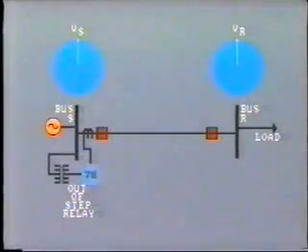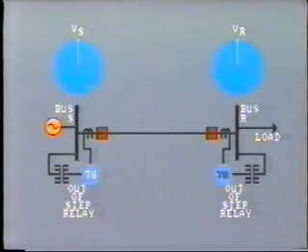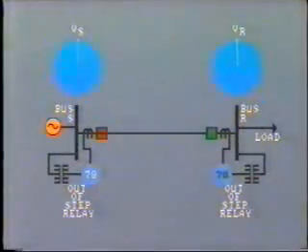The time interval between the first and second zone operation is important. The relay is set to indicate an out-of-step condition where the time interval is 60 milliseconds or more, since short time intervals, say 5 milliseconds, would probably be caused by a fault on the line. The out-of-step relay at bus S operates to trip its breaker. A similar relay located at the receiving end bus operates to trip the breaker at that end.